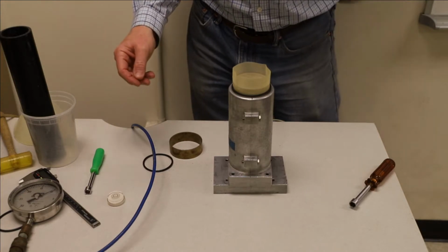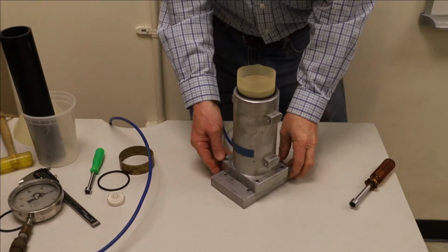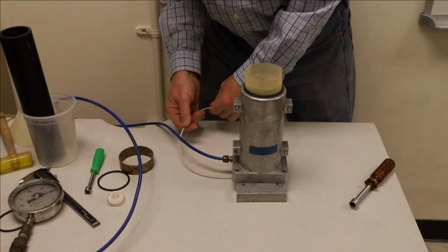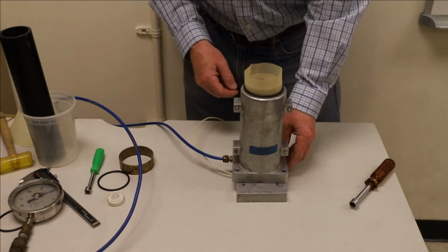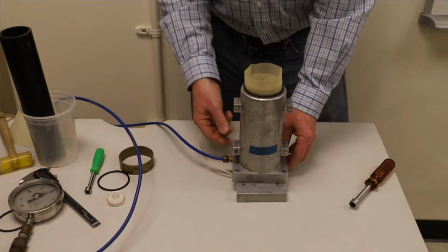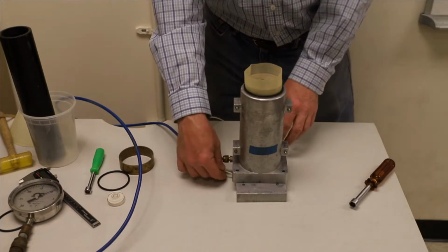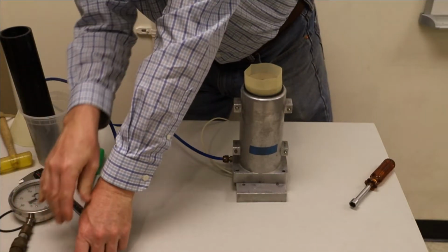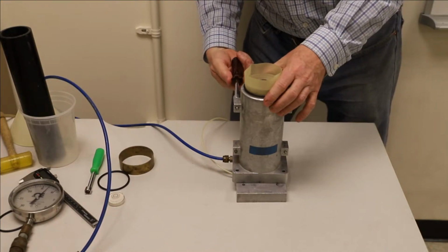So we've connected the second vacuum now, the one that goes to the inside. So let's turn the system so you can see that. So this is the fine tube here. That's the one that goes up into the bottom of the base cap and connects to the inside of the specimen itself. The blue tube is the one that is holding the membrane out against the mold, and we don't need that anymore as long as we have vacuum in the specimen. So we're going to disconnect that line, and we're going to disassemble the mold.